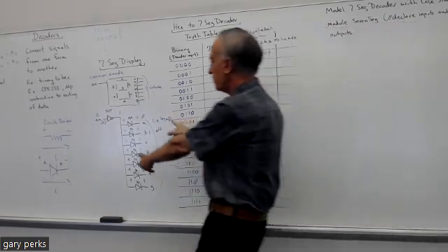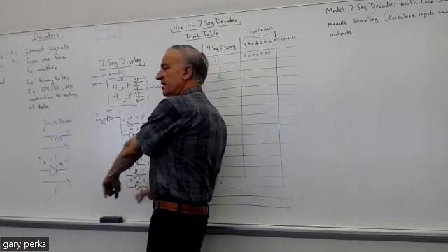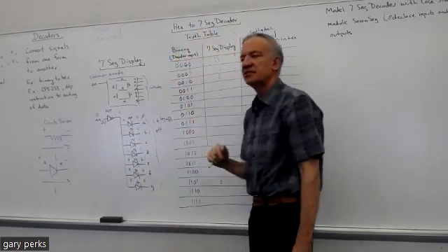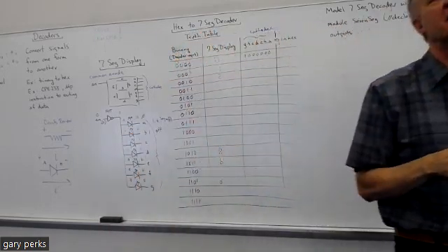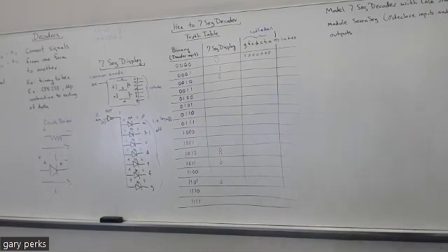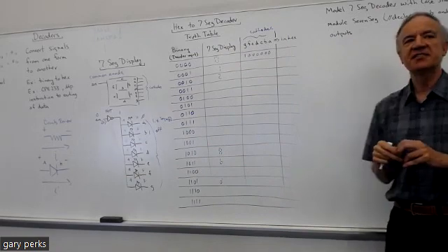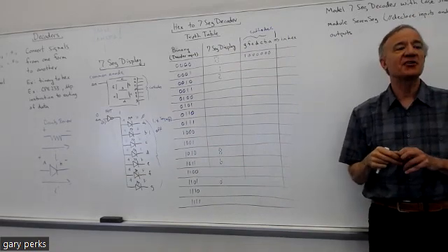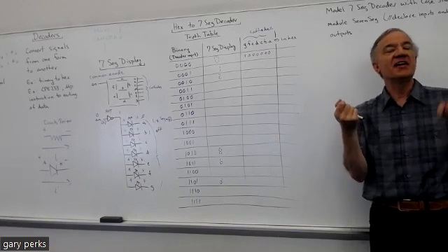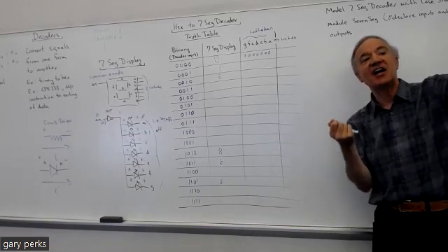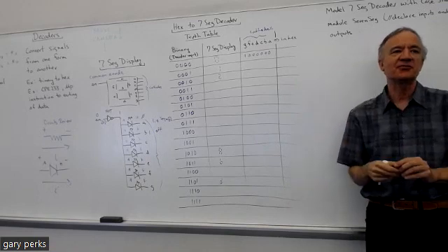Because that would put equal voltage on each side of this LED, and therefore no current, therefore no light. So you selectively apply voltage to keep a light off. Right, yeah, in this case. You would make the cathode like 5 volts, and that's because on the other side is 5 volts. So again, you'd have equal volts and no current.